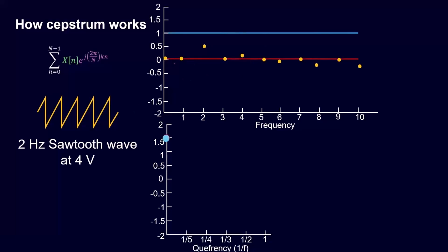And one thing I'll notice in the frequency domain, a lot of frequencies, if I'm starting at 0 hertz, are 0. So this is actually going to have a high correlation. Now, Olaf, is it super useful to us to know what's going on at 0 hertz in the Cepstrum domain? In practice, not. Nobody looks at this point because it's more or less the DC component of our logarithmic value, so it has no information. Yeah, so all Cepstrum graphs will probably have a high zeroed component, and that's just because a lot of the frequencies are at 0 or near 0, so that naturally this is going to fit those lines.